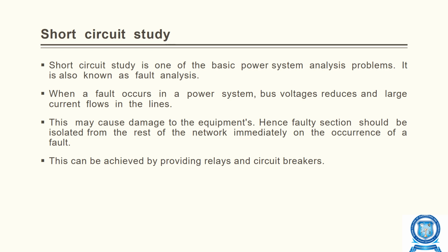The faults are classified into two types, that is short circuit fault and open circuit fault. The short circuit faults are further divided into two: one is symmetrical fault and the other one is asymmetrical fault. Symmetrical means balanced fault, and unsymmetrical means unbalanced fault. So short circuit analysis or short circuit study is one of the basic power system analysis problems. It is also known as fault analysis.